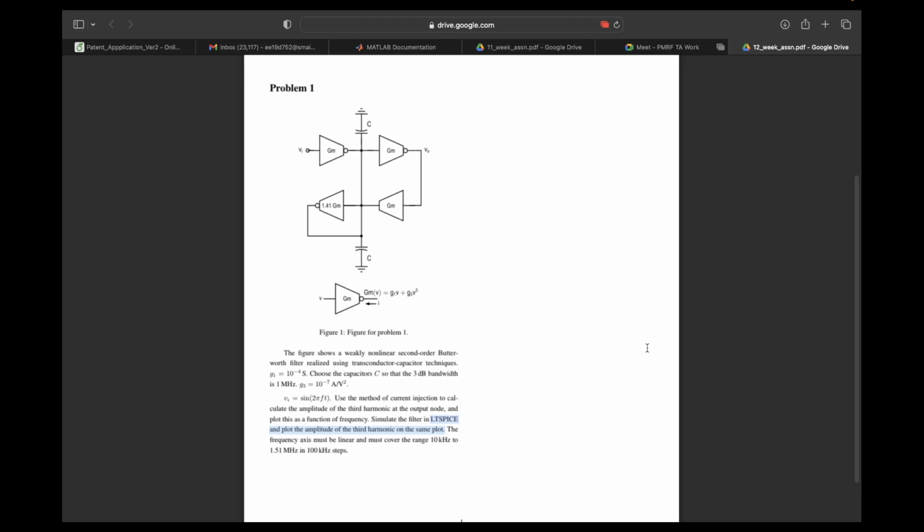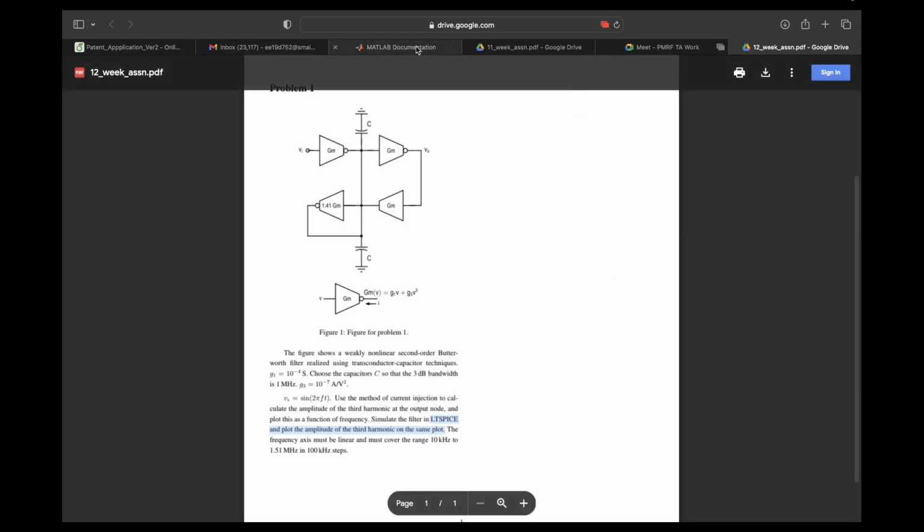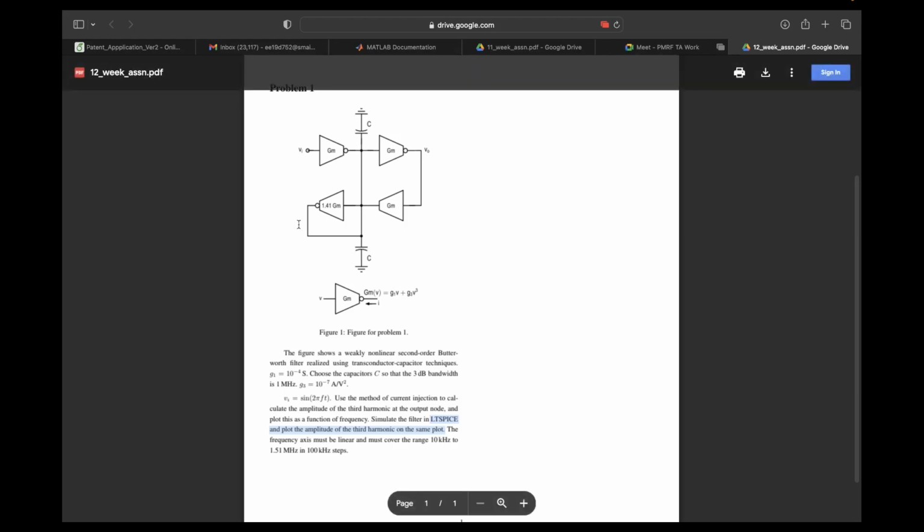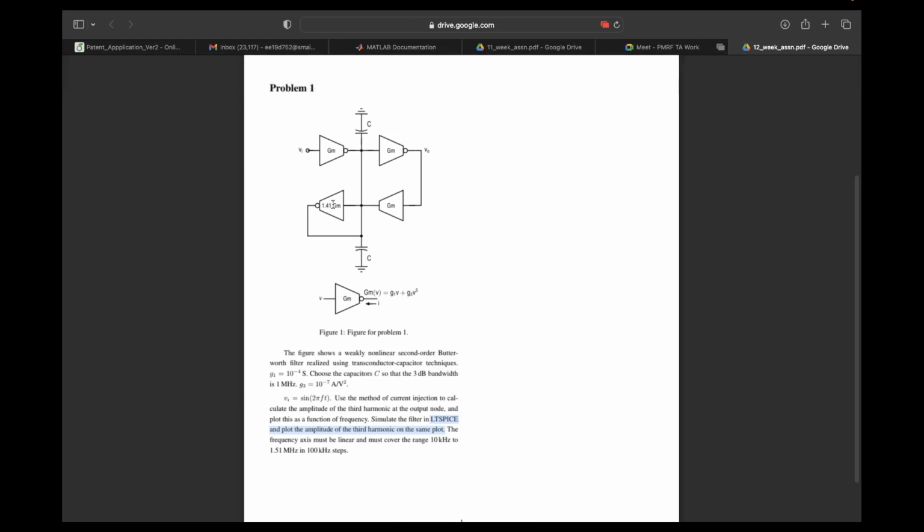That will be fine, sir. That is operational transconductance only, no, sir? Yeah, so you will have to use the same behavioral current source in that case. The behavioral current source is perfect, sir. Here that bubble is there, that is a negative, no, sir? Yeah, that is to denote that current is being sucked into the transconductor.